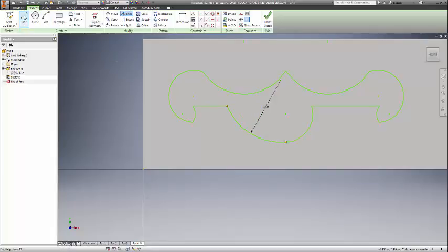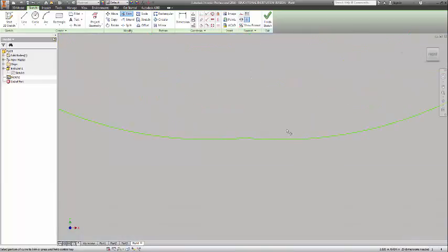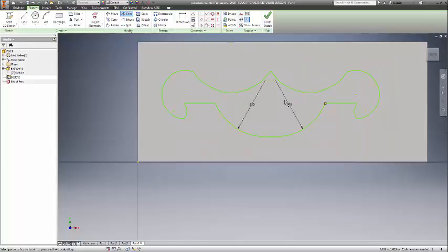Okay, let's do the same thing again. Let's do arc, 3-point. Okay, again, I click, see the little green dot, perfect. Green dot, perfect. And that one's 0.95. I can just type in 0.95. It's going to give me that exact shape. And let's go to trim, trim, trim. If you notice, I have a little extra on here. Let's trim that. Very nice.